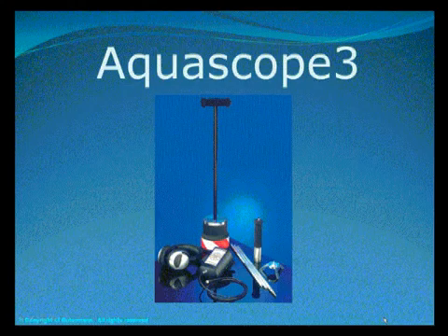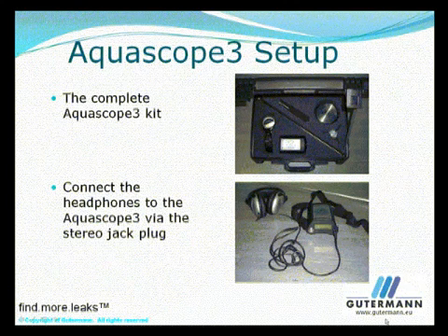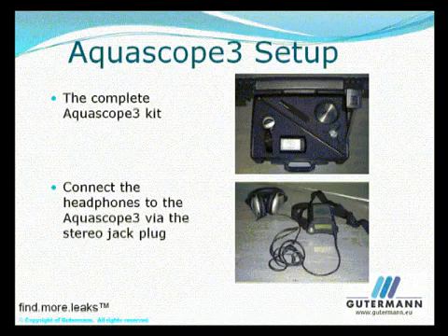Now that we've provided you with an understanding of the theory of leak detection, it's time to explain how to set up your Aquascope 3 and use it to find leaks. Aquascope 3 Setup. Connect the headphones to the socket on the control unit located to the right of the display.